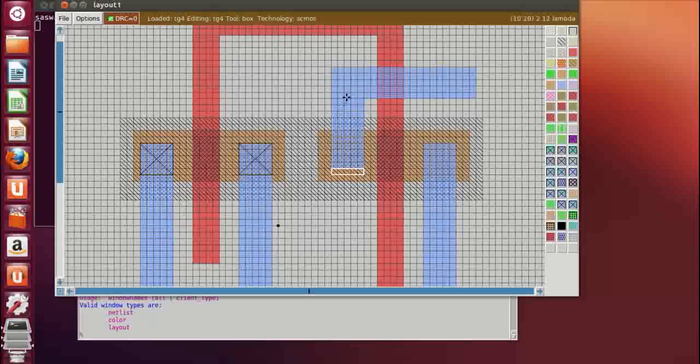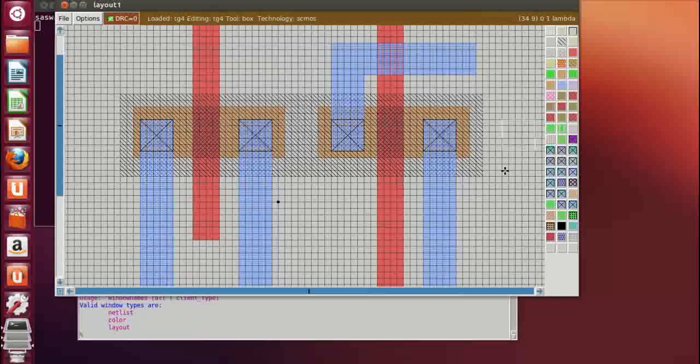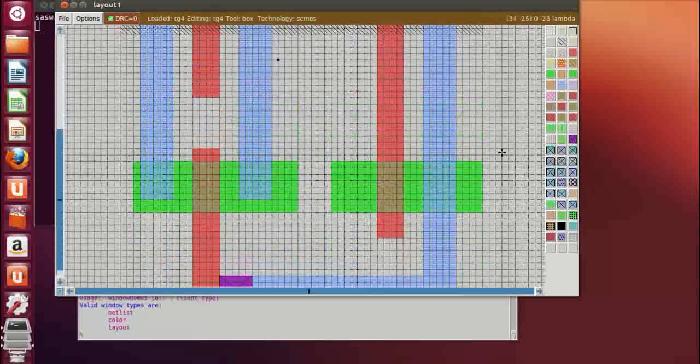Okay, so here similar way, select, and this is the PD contact. I want to extend it by a metal layer. I want to see uniformity in my layout. So that's the reason why I keep on extending. Now the PD contact. This is also my PD contact. So we had there PDC, here it is the PD contact, and here the NDC, N diffusion contact.